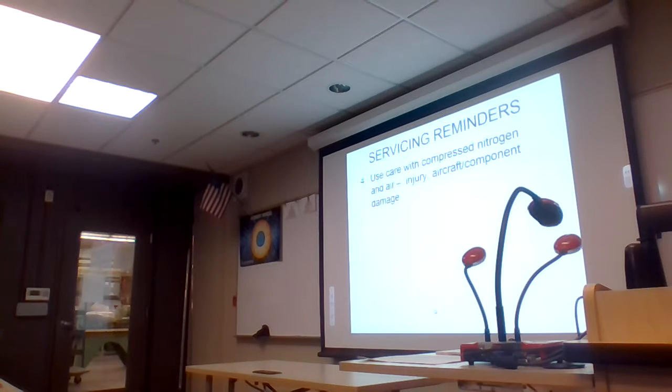Accumulators are serviced with nitrogen for a reason: it helps to prevent an explosion, because nitrogen is pretty much an inert gas. It doesn't support combustion. On a lot of large aircraft, we also inflate tires with nitrogen. When that rubber compound gets hot, we're trying to do everything we can to prevent an explosive environment. So the large aircraft tires are generally inflated with nitrogen.